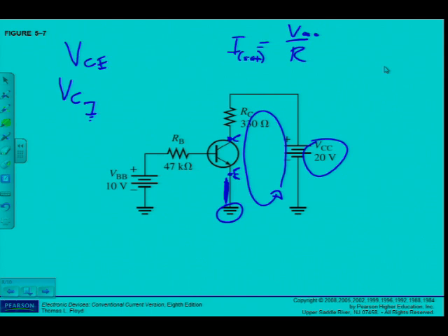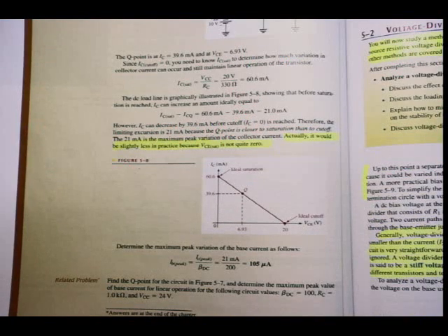I know, those are two C's actually. VCC. And what is the resistance around this circuit? RC. There is no other resistance in that circuit, ne? So maximum current is going to be determined by my supply voltage and the resistances around this series circuit. Simplified a bit, it is not exactly true, but let's stick with it at this stage. Maximum current is then VCC divided by RC, and we get a value of 60.6 milliamperes.